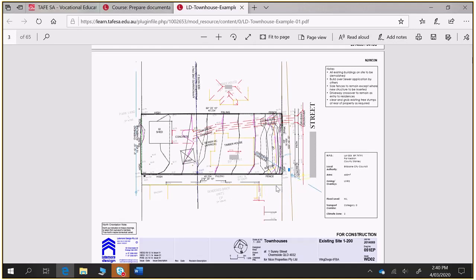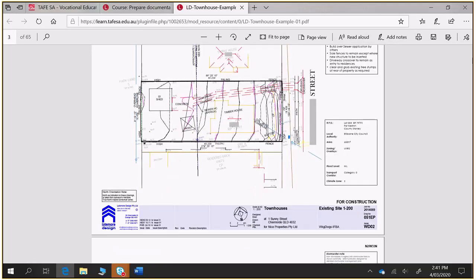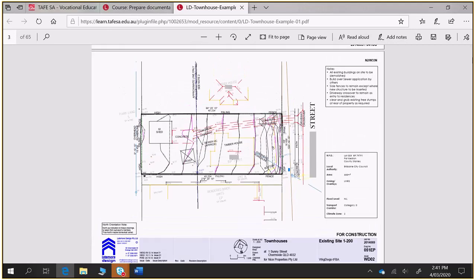And then, what you're not doing is dimensioning, you're not showing exactly what the dimensions are to their place, because you don't know. You can find out roughly from Google Earth or SA Map Viewer, but you don't know, so you don't dimension it. You can give some approximates if there's something really important about that. But that's pretty much what we'd show on our site analysis plan. With yours as well, you have some vegetation to show. It's not so much about what the vegetation is doing on our site, but what the vegetation is doing on the street and the neighbours. So that's your site analysis plan.